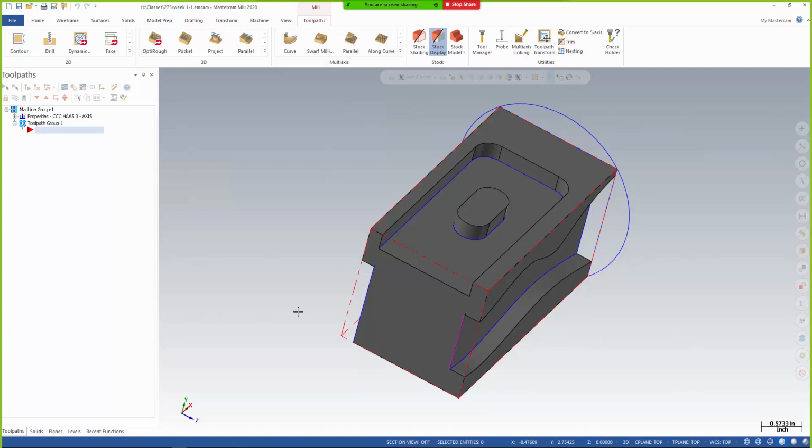If you're running a lot of different tools and you're only running one side at a time, you're going to have probably 4 times the number of tool changes, 5 times the number of tool changes that you would otherwise. So depending upon how fast your machine is, and this is really where you've got to be thinking, some machines rotate very slowly, and in that case, the tool change time is actually quicker than the rotation time. So be thinking in those terms. How fast is my rotation?